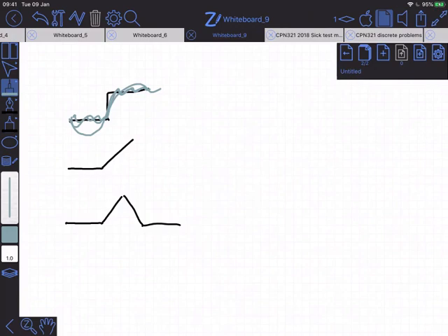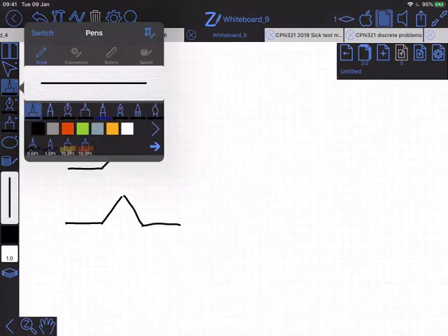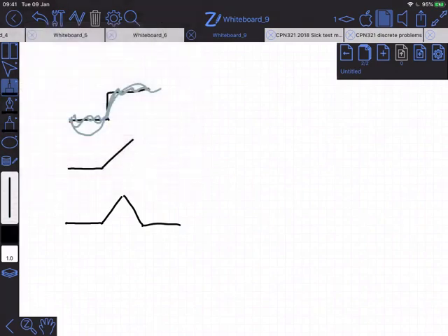So another way of thinking about band limiting is almost like a slope limit, or actually a smoothness limit. Here's what a band limited version of the step would look like. That is a step that's been taken through a brick wall filter, and all the high frequency components have been removed. That thing can be approximated by the first couple of Fourier series terms, because it's got this smooth behavior.